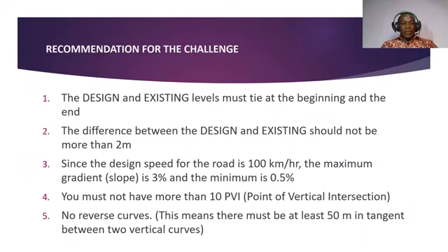So these were the recommendations I gave for that challenge. I said that the design and the existing must tie at the beginning and the end. This is a personal recommendation, and it happens, of course, sometimes, especially when the road is linking to an existing road. So you don't want to make the beginning higher, things like that. Also, the difference between the design and the existing should not be more than 2 meters. That is the cut and fill.